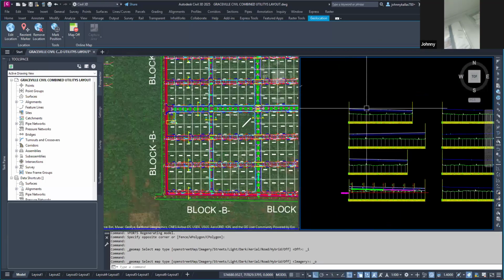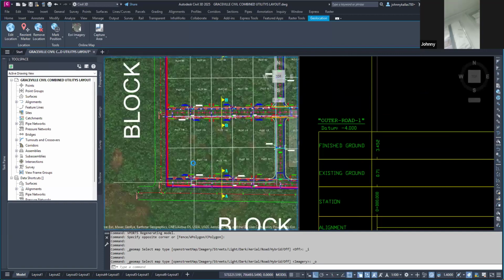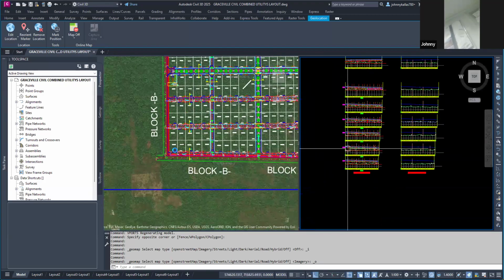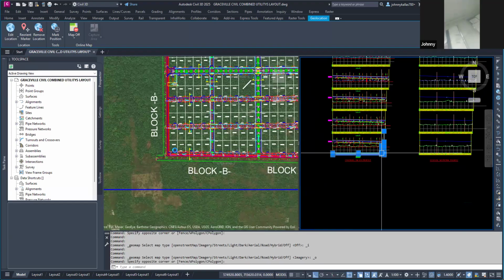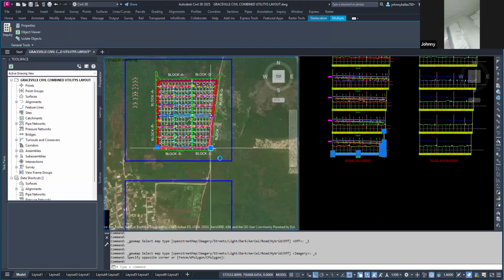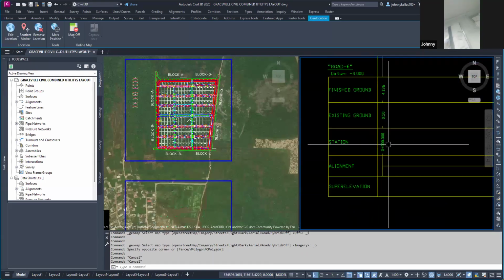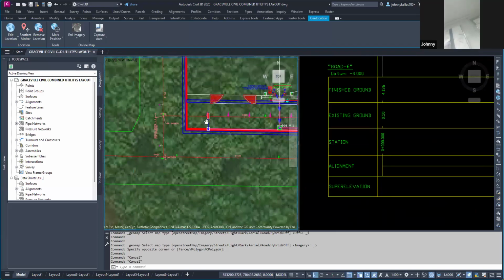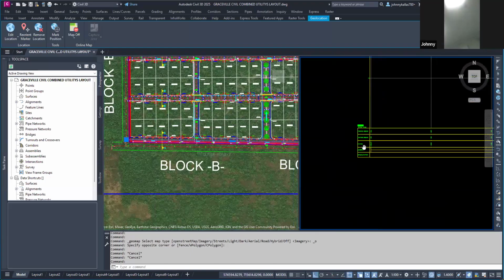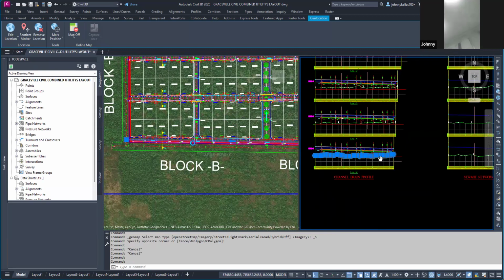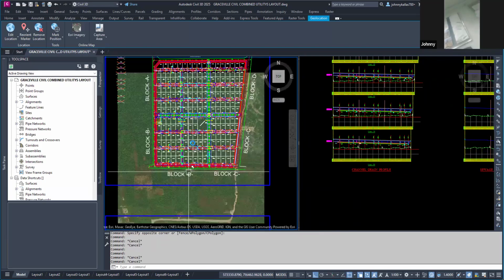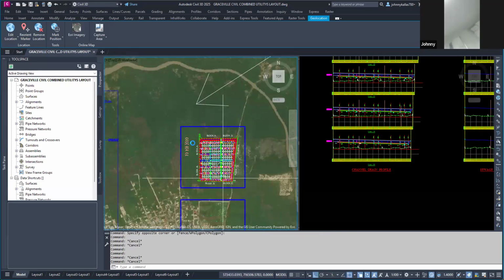This is road 6, which means this road, with this alignment. You can see this point here is at station 0, so this is station 0 for road 6. This is the existing ground level. We raised up the road around 3.5 meters, so the water can flow from here through to the canal, as we said before.